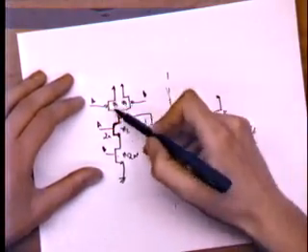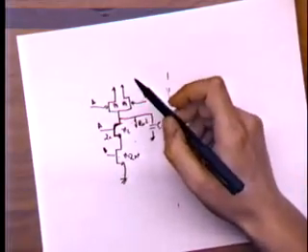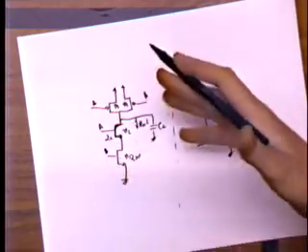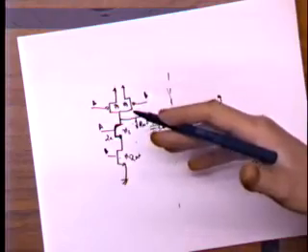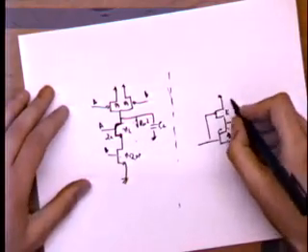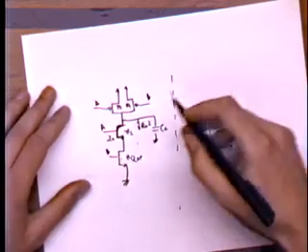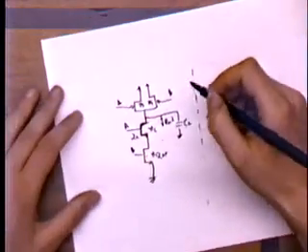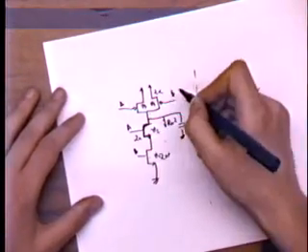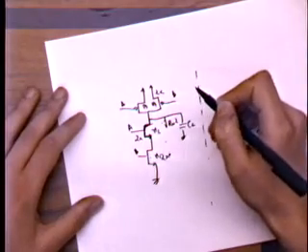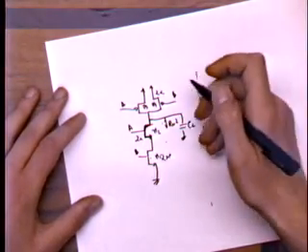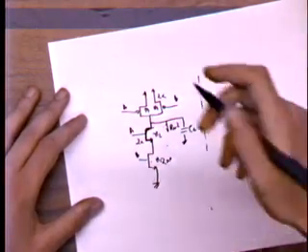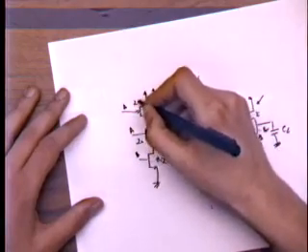Now let's look at the PMOS devices. So in the PMOS case, the pull-up is only one transistor, and we again want the same driving strength for the pull-up that we wanted for the pull-down, right? So in the inverter case, the pull-up was one transistor with size 2, and here again we have only one transistor. So the size of this transistor is going to be the same. Because remember, in the worst case, only one transistor pulls up the output in this gate, okay? And this is the key. So we're going to size both these PMOS to be 2x, right?